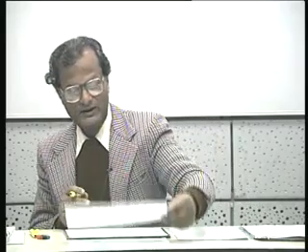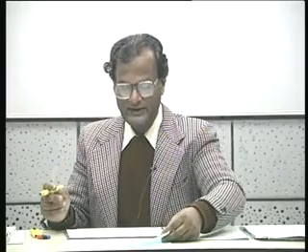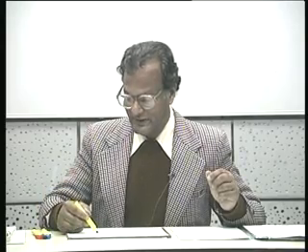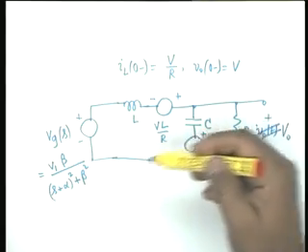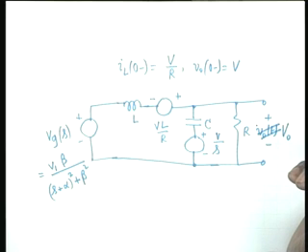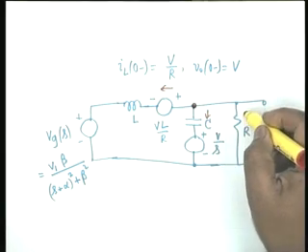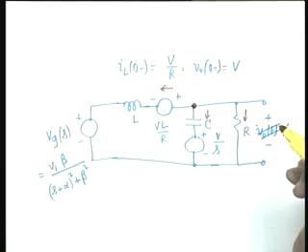Okay. Now, if you look at this circuit, what approach should you follow to derive the value of V0? Pardon me? Thevenin's theorem. Thevenin's theorem will require finding out an open circuit voltage here and the impedance looking back and so on. That is a simpler way. Just node equation, just one node equation. This node whose value is V0, and you sum up the currents, this current plus this current plus this current, sum up to be equal to 0.